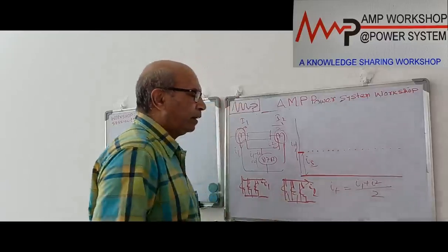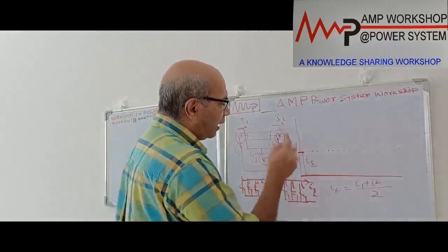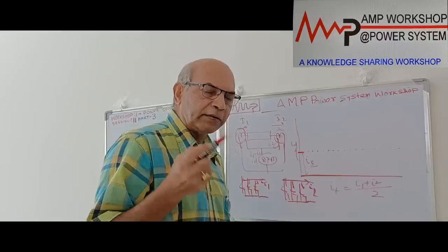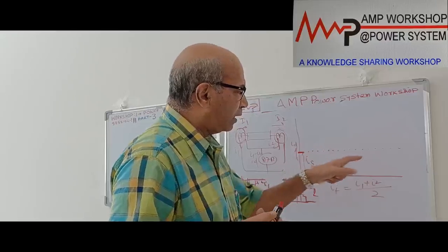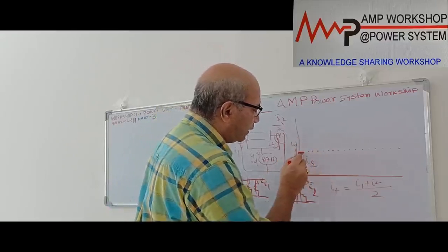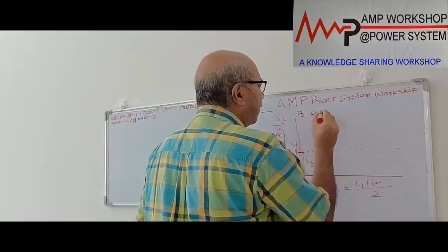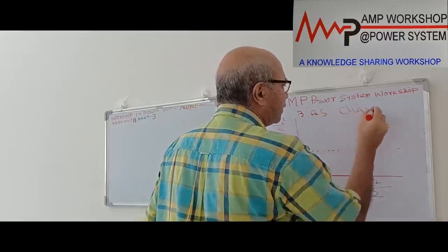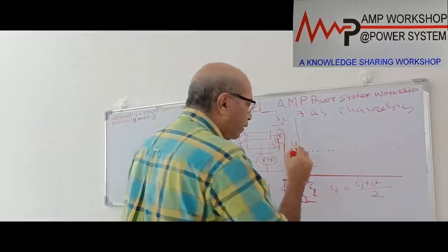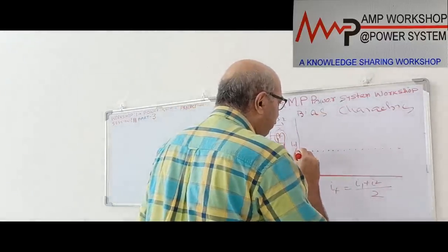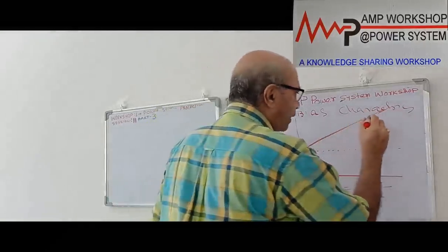This is the IS current. Now, when we incorporate the bias characteristics in this relay, what do we see? In the conventional overcurrent or conventional differential scheme, the relay will operate based on this IS current. But when we include the bias or restraint characteristics in the relay, the relay will not follow this curve. Depending on the bias, the relay will follow this type of characteristic. This will be the relay characteristic in the case of bias.